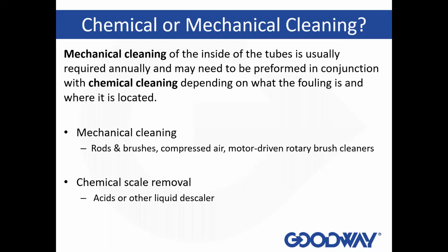Not too many places are still doing that, but once in a while I've been in mechanical rooms and still see rods laying around that they use as a backup here and there. Some places will use compressed air. Again, that can help you somewhat, but generally it's not going to get scale off the walls.